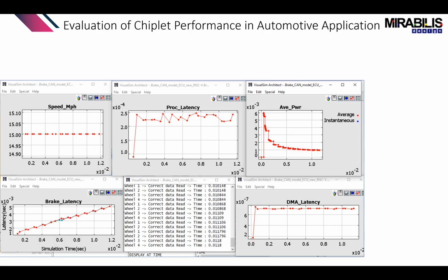So it's like less than 10% impact on your system. But what you notice is the sudden spike in the initial power, and then after that it drops off. But the worst is your brake latency. Notice it's constantly increasing, which means at some point you're going to start off where you were braking within about 400 feet at 60 miles an hour to it suddenly becoming 1200 feet.